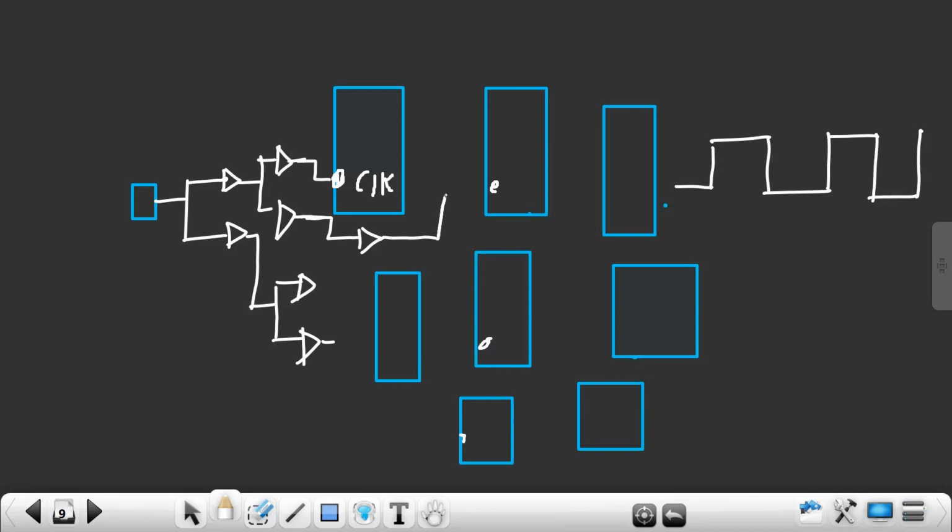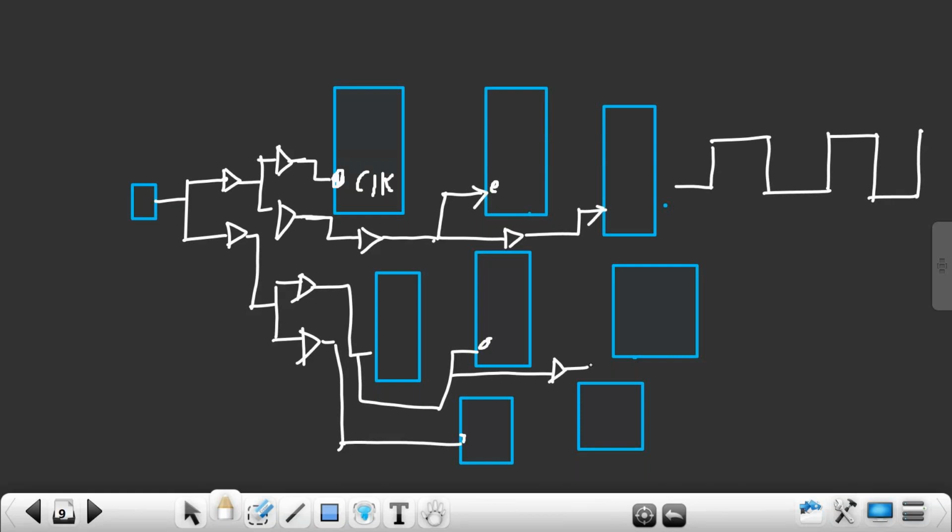Now what you do is go and connect here. So long net, so what you do is use one more buffer, go and connect here. Like this, we build a clock tree to connect your flip-flops. So for a long net, use one more buffer and connect here. Here you have a long net, use one more buffer and connect here. Like this, use inverters and buffers and connect to all the flip-flops by inserting extra buffers.